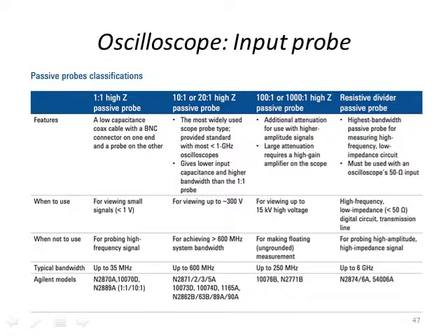And then you can see this is an example of an input probe and how to choose. You can go through here what to use, what not to use, and when to compensate at different frequencies. But essentially it's based on the transfer function, this little summary. So these are for passive probes. There are also active probes where you can amplify as well. So the probing functions are extremely important for oscilloscopes.